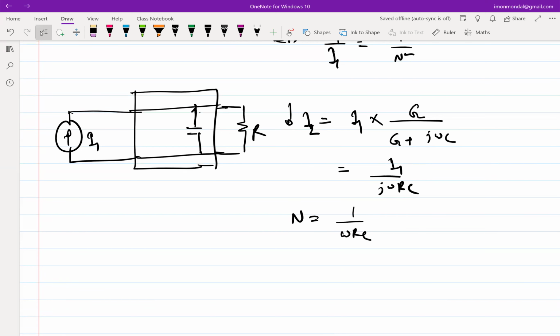So this will take care of the real part, but I still have an imaginary part available. So how do I resonate out the imaginary part? I have to put an inductor, but in series or in parallel? If I put it in parallel at resonance, what is the current through R? It is I1. It's not stepping down. So I have to put it in series.